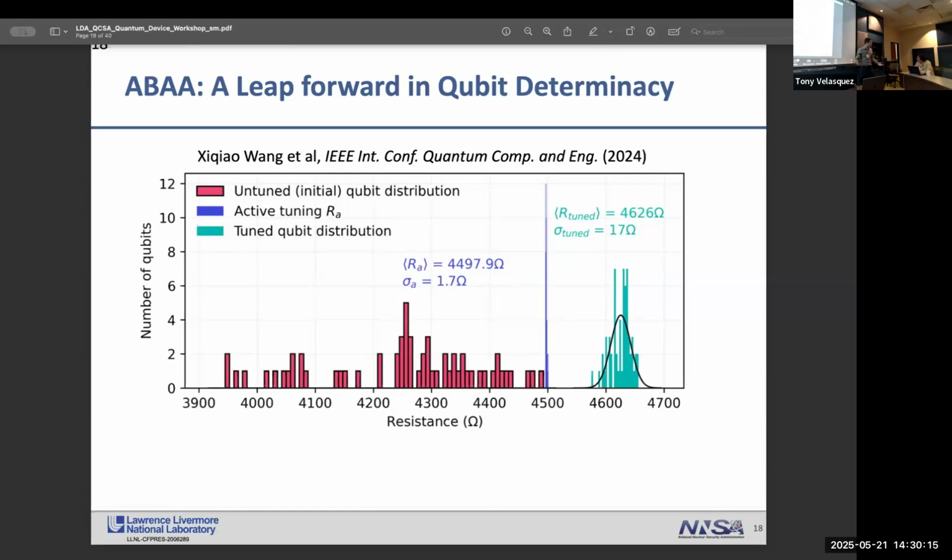Sometimes I use KLayout all the time. Sometimes you have to, but when we're kind of organized, we write Python scripts to make GDS files, and many people in the field have spent months writing really annoying scripts to create GDS files. I think these AI tools are very powerful at automating that sort of thing and converting concepts about geometry into scripting to create geometry. So useful both for junction layout and circuit layout broadly.